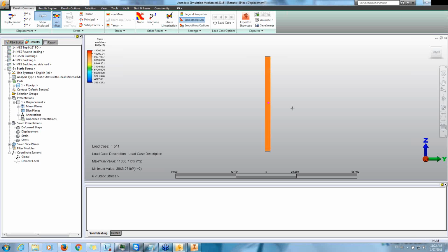So this tells me that I'm okay with the stresses, but even though my stresses are not that high to cause any failure, my buckling multiplier is 0.8, so I'm going to buckle before I fail due to stresses. So if indeed my load is 1,000 pounds, this thing will buckle and is not a safe design.